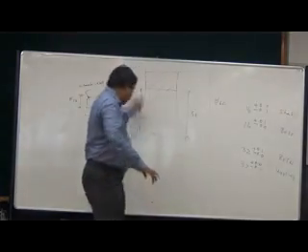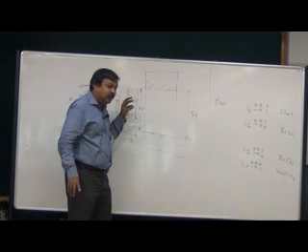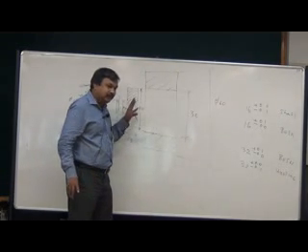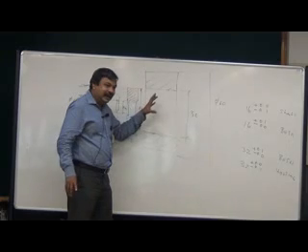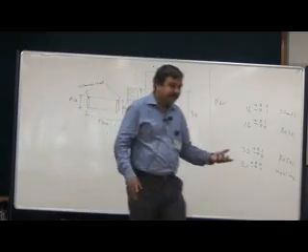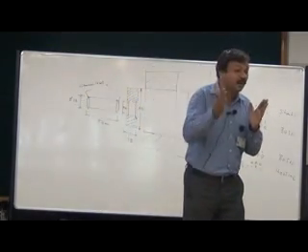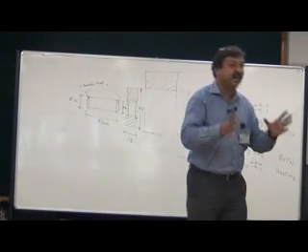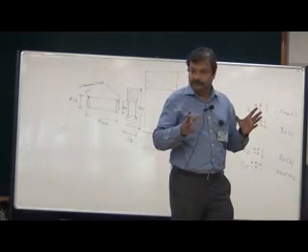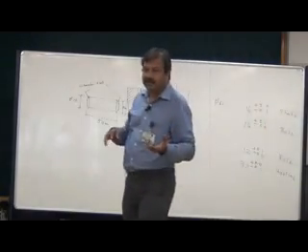Now, coming to the bush, the outside diameter of the bush is going to be slightly larger than the inside diameter of the housing. So what is the effect? The material of the bush and the material of the housing are going to interfere. There are many ways to achieve this interference.